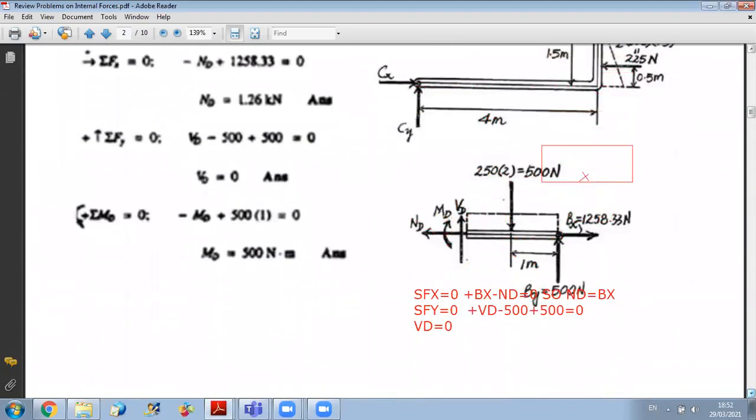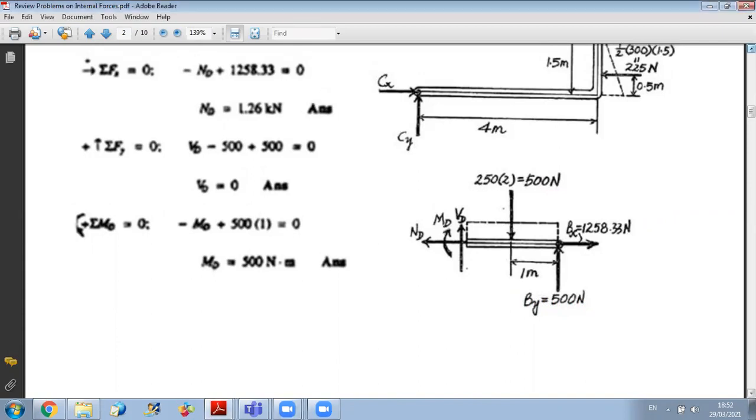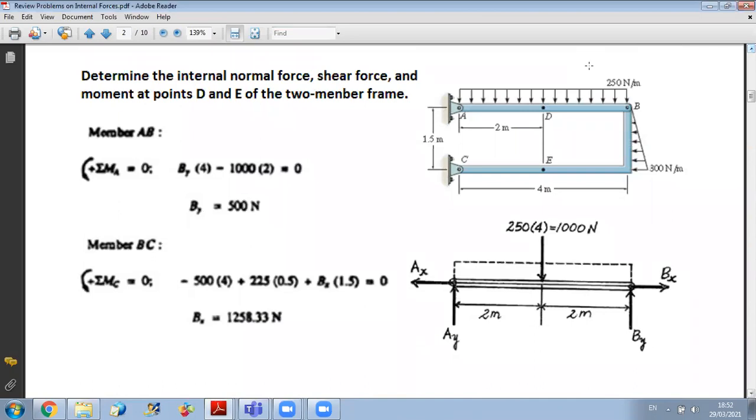Okay. So here, then in the second step, I have that, and here you have the symmetry. You have this part AB, and AB is subjected to this rectangular load. So here AB is undergoing a symmetrical load with respect to point D. This is why the shear at D, which is just at the middle of the beam, should be 0.